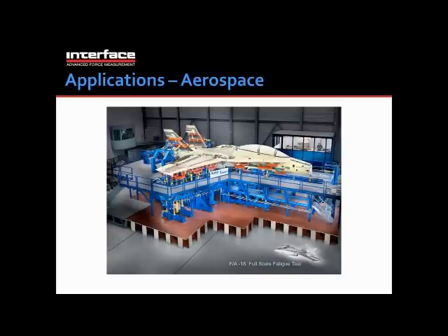But as you can imagine, these airframes get cycled millions and millions of cycles to ensure that the planes stay up in the sky. So some challenges exist there to ensure that the load cells will endure the fatigue cycles, and we will often supply multi-bridge load cells, where you have several discrete bridges on the sensor so that you can have individual signals, again, running to the DAQ or to the hydraulic control system.